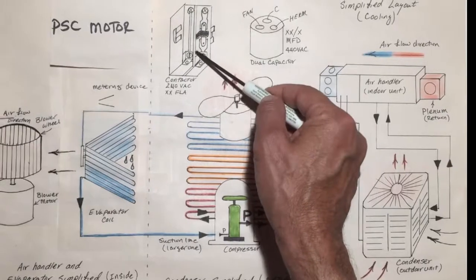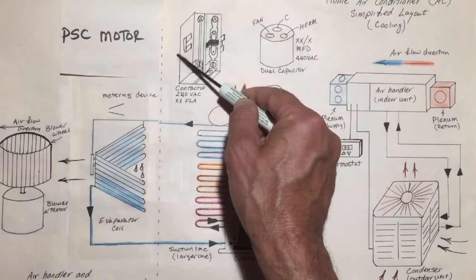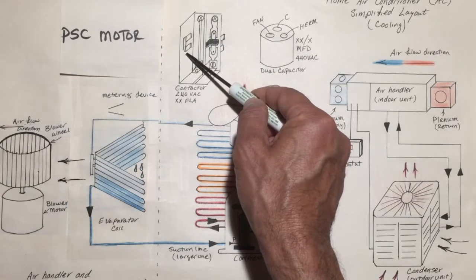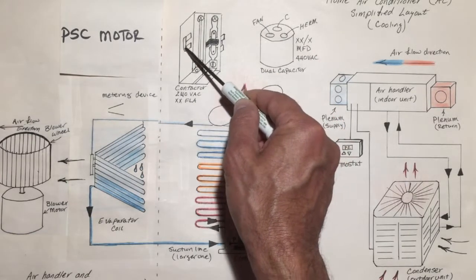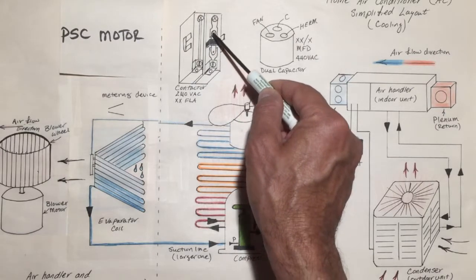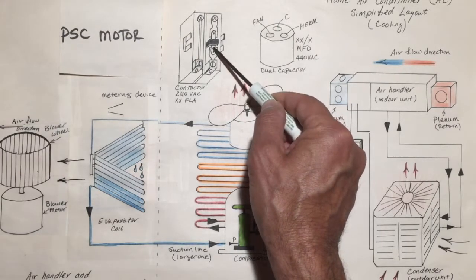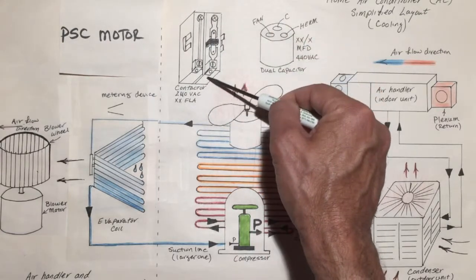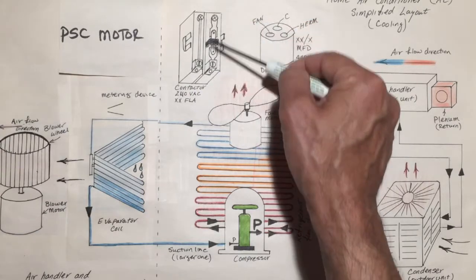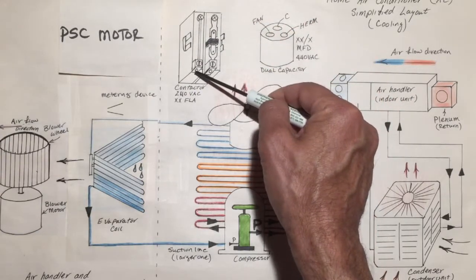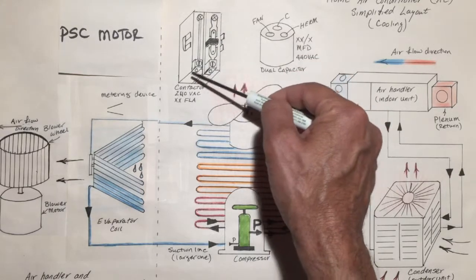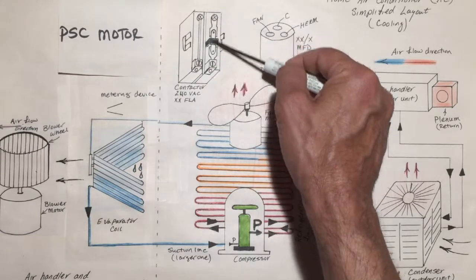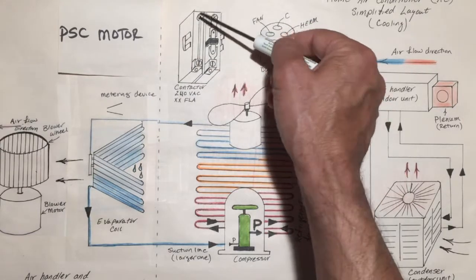And for this contactor to work, there is a relay, there's a coil down below here. Again, we'll look at an actual one that, upon having 24 volts, this lever here pulls down, and we have a current flowing from this leg to the input side to the output side. This is a one-pole contactor. I drew it as a one-pole because I'm going to show you a one-pole. Basically means that only one leg of the 240 is getting switched. The other leg it's hardwired in.